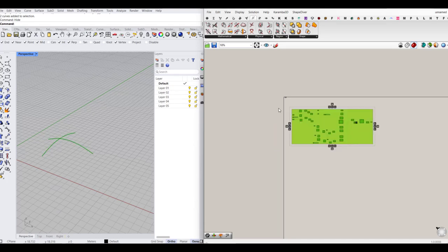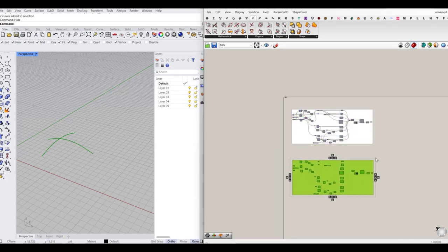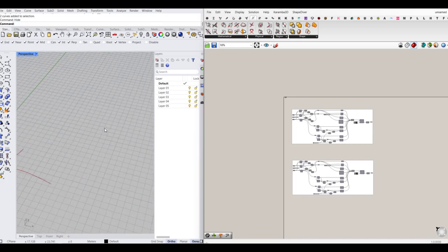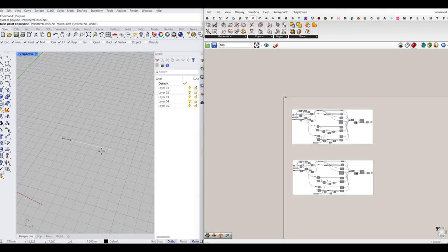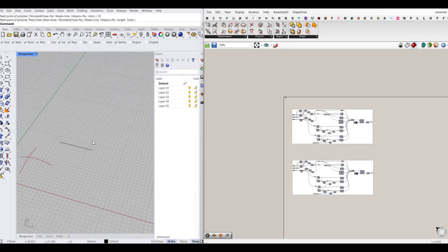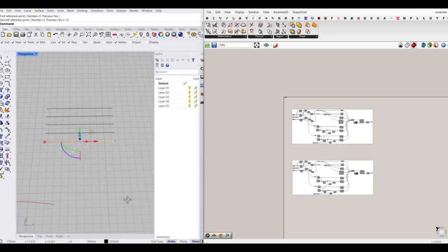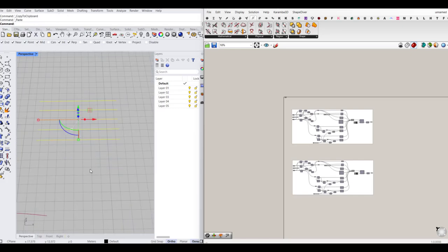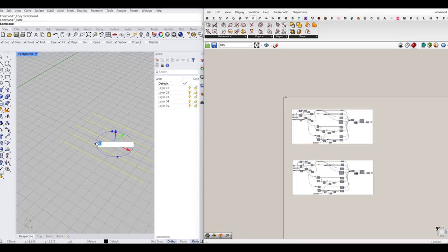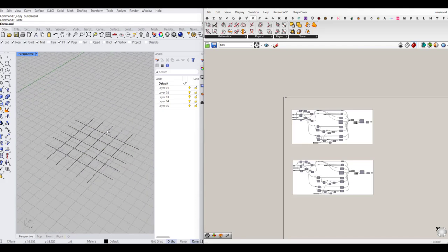So I will copy this part, bring it here, and this time I will also draw it on my Rhino screen with the size of 10 in one direction, and I will use array linear, make, let's say, 5 elements with a distance of 1 or 1.5, and I will also copy them, make a 90-degree rotation, and this will be my second set of points.